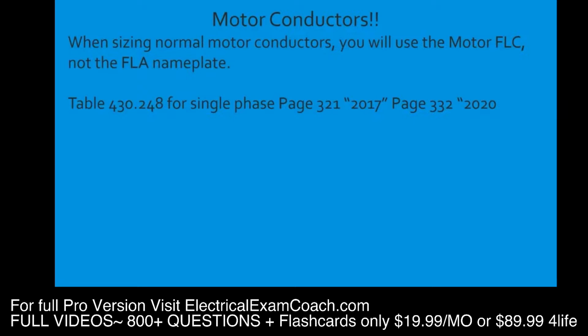Okay? One thing I want to note is that these are nominal voltages. So, although it says 115 at the top, it would also include 120. Although all the way at the end, it says 230 volts across the top of the black bold headings, you could still count 240 in that. These are nominal voltages. Another tip I want to give you is that even if the motor is a single-phase motor, but your question states 208 volts, you use whatever column your question states. Don't try to use reasoning and say, well, 208 is only three-phase. Whatever your question states, just do it that way.